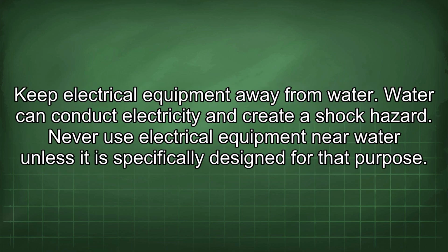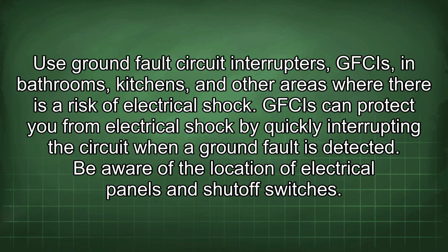Keep electrical equipment away from water. Water can conduct electricity and create a shock hazard. Never use electrical equipment near water unless it is specifically designed for that purpose. Use ground fault circuit interrupters, GFCIs, in bathrooms, kitchens, and other areas where there is a risk of electrical shock. GFCIs can protect you from electrical shock by quickly interrupting the circuit when a ground fault is detected.